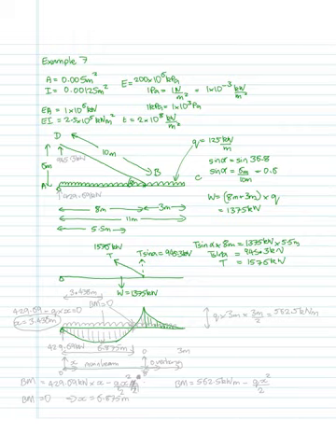So that's going to be 945.3 kilonewtons. And so the reaction at A is going to be the total force applied to the beam, 1375 minus 945.3, and that will give you 429.69 kilonewtons.